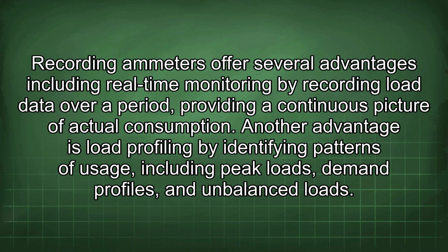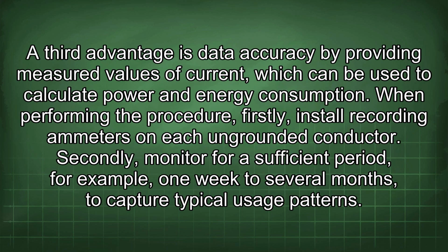actual consumption. Another advantage is load profiling by identifying patterns of usage, including peak loads, demand profiles, and imbalanced loads. A third advantage is data accuracy by providing measured values of current, which can be used to calculate power and energy consumption. When performing the procedure, firstly, install recording ammeters on each ungrounded conductor.